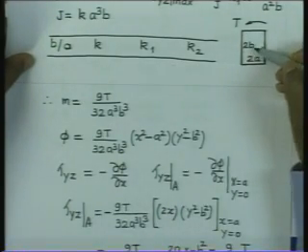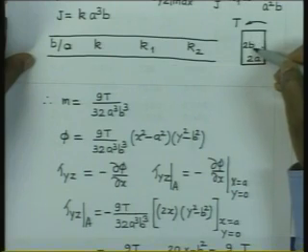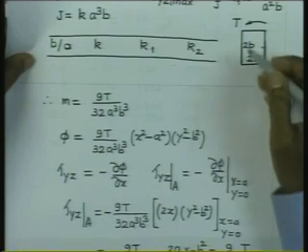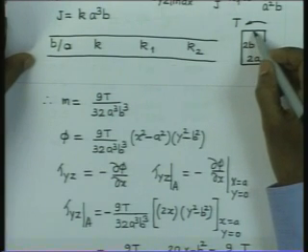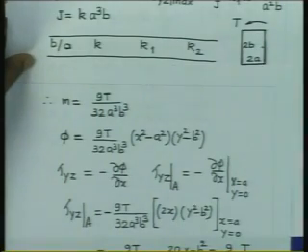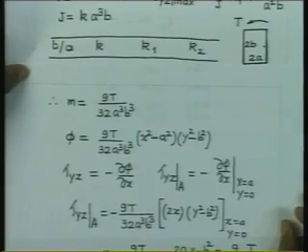You will find a similar picture if you calculate tau xz stress. It is going to be highest there, and it is going to vary linearly from this point to that point, and the maximum stress is acting at this point. However, this maximum is lower than the maximum here, that is why this is the most critically loaded point. We will try to look into more of the physics a little later.